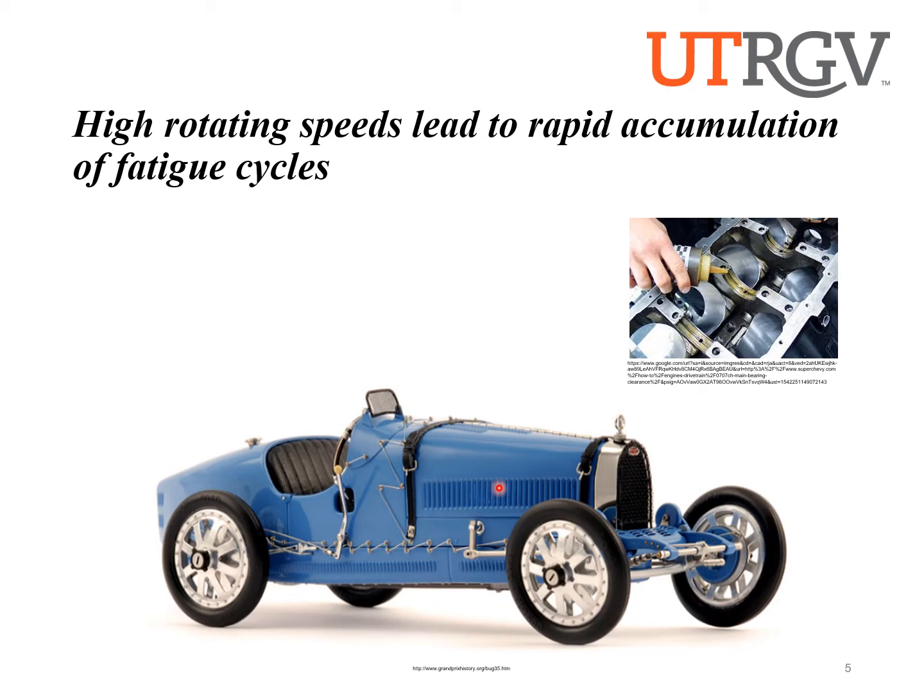Again, because by around the 3 to 4,000 mile mark, all the bearings inside have already accumulated so many fatigue cycles that they start failing and the engine just tears itself apart. That's why if you were to open up your car engine right now for a modern car, well, we did away with the rolling element bearings for the crankcase, for example, and now we have sliding bearings, which is this picture over here.